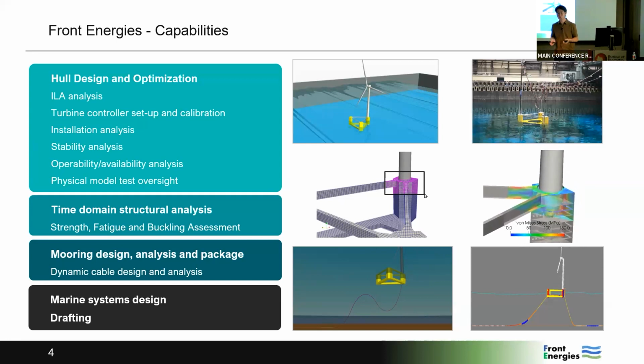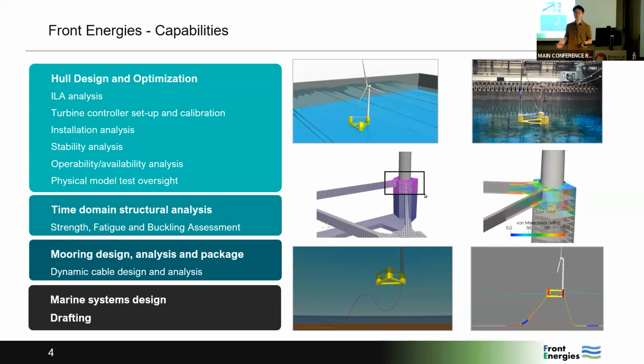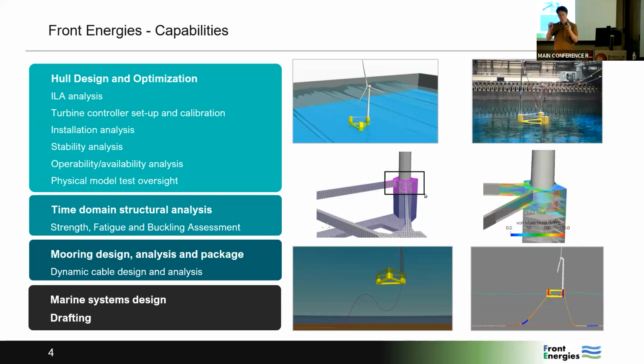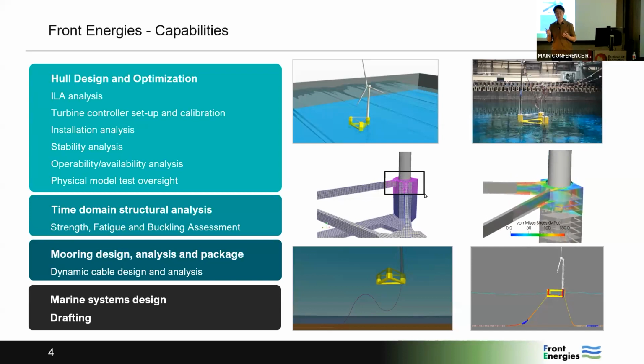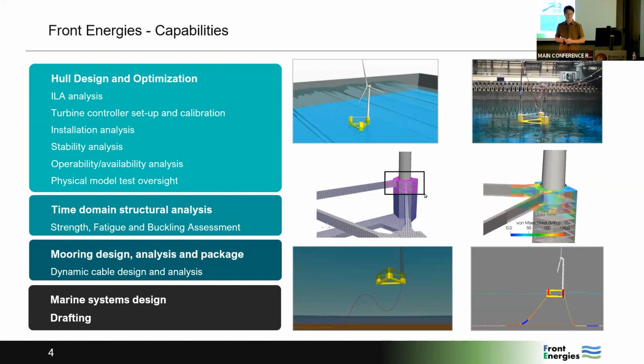Most offshore structures undergo a physical model test to confirm their performance. This model test is also used as a reference for numerical simulation. The numerical simulation is calibrated based on the model test, because we don't have any full-scale floaters. Before building full-scale floaters, we do the model test first: we simulate the scaled structure, put it in a well-controlled environment, and get some response. Using this response, we calibrate the numerical simulation, and using this calibrated simulation, we do the design and analysis.